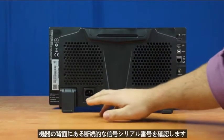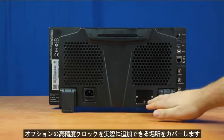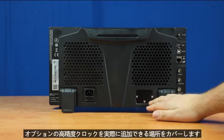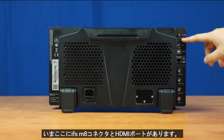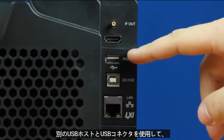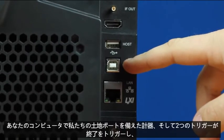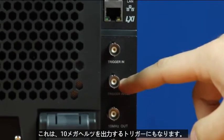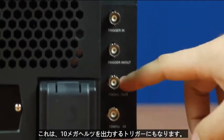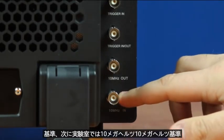On the back of the instrument, we'll find the serial number, along with the power port and fuse cover. Then we can find the cover for where you can actually add an optional higher accuracy clock at any time. And right here we have our IF SMA connector, the HDMI port. Then we've got another USB host, along with our USB connector, so you can control the instrument with your computer, our LAN port, then 2 trigger ins, and this one can also be a trigger out, our 10 megahertz out, in case you wanted the reference, and then a 10 megahertz in for a laboratory 10 megahertz reference.